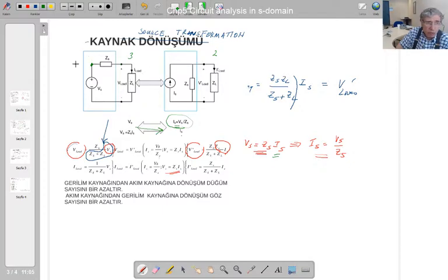If a circuit is given to you, consider that ZL represents many of the elements included in the circuit. And then you are analyzing this circuit by using the node voltage method. Now this conclusion tells me that if I do the source transformation, I reduce the number of node equations by 1, isn't it? So you can write one less equation if you do the source transformation from left hand side to the right hand side. That is a benefit.